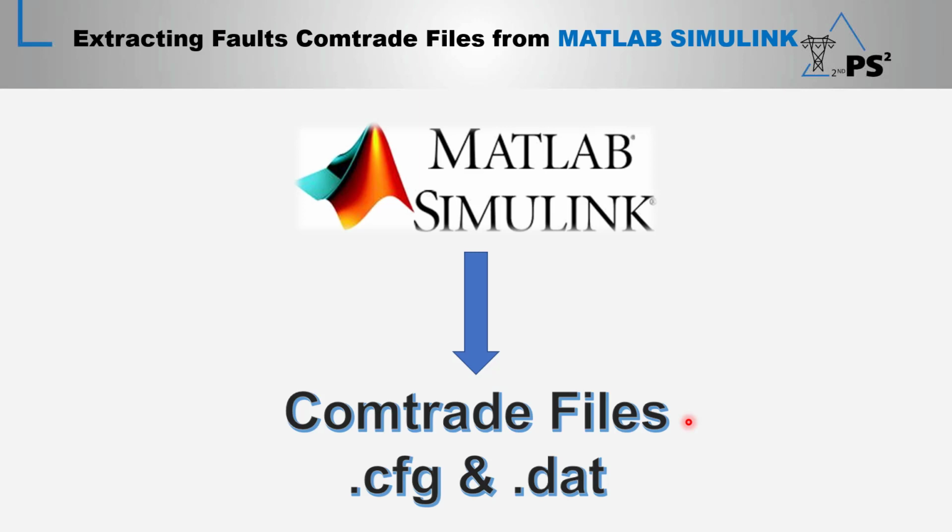We can import this Comtrade file into the Relay Tester software, which we will use to re-inject into the protection relays, to make sure that if this fault happens in the network in real time, the relay can trip and the other relays will not trip.